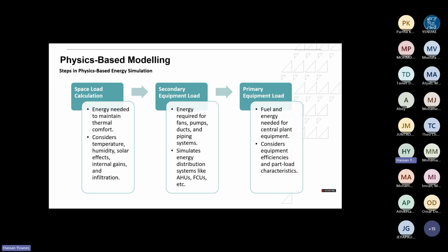So I need to build that performance map and make sure I use that in my software. Now the software would have some typical curves for the different equipment. It would probably be okay to use for fans, maybe pumps, but for chillers in particular, you'd need to get a performance map from the supplier. And that happens by asking them for different points.